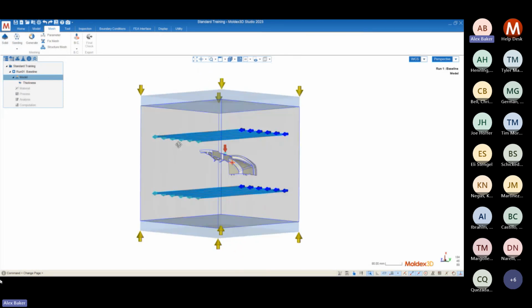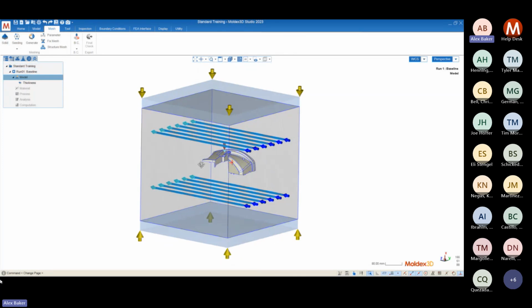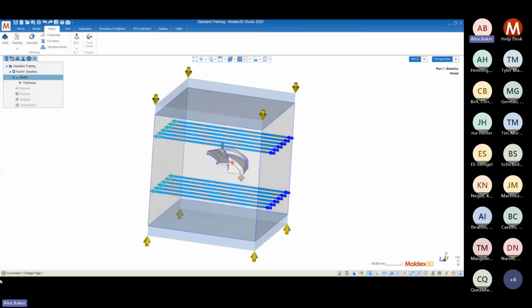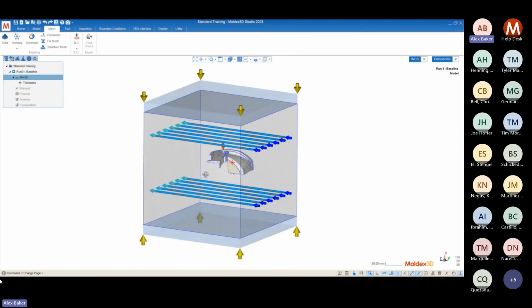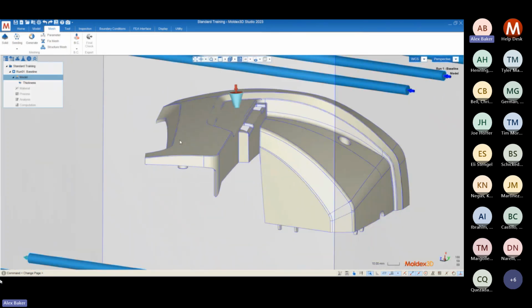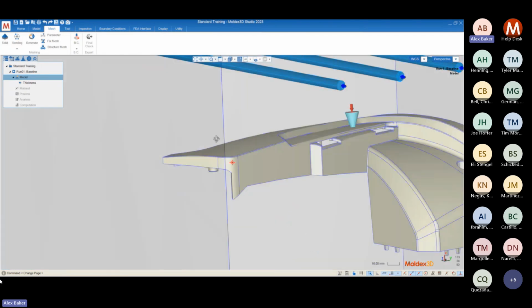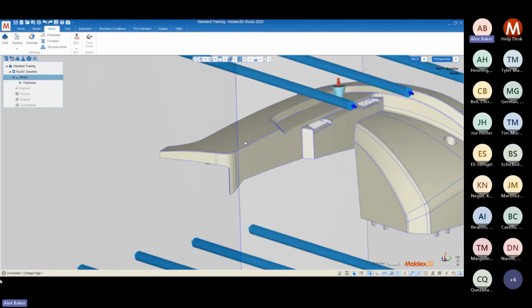And when we're talking about meshing in the solid mesh specifically, in the solid meshing style, I should say, there's two meshes that are going to be created for every geometry object. There's going to be a surface mesh and there's going to be a solid mesh. A surface mesh is going to be breaking down all of the individual surfaces in our geometry into a series of triangular surface mesh elements. And then we're going to fill in those surface mesh elements through the thickness of our part with a solid mesh. All right, so there's two meshes that we need to specify the parameterization for.